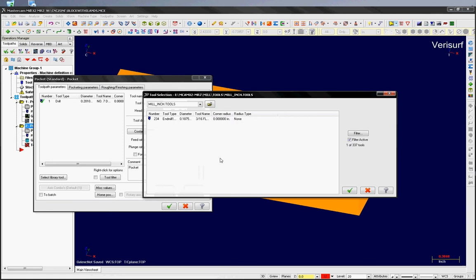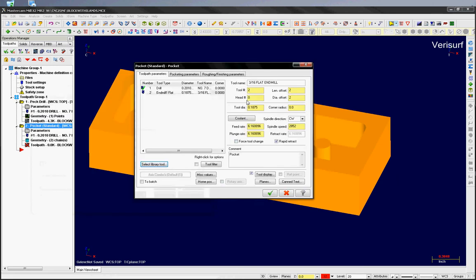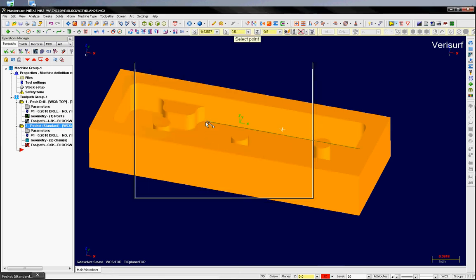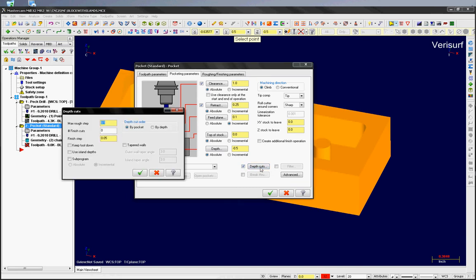I'm going to go ahead and select a tool. I will use a 3/16 at this time. Like I said, not worrying about feeds and speeds, but I am going to worry about depth. Making sure that I get the bottom part of my depth, my pocket there. Maybe some depth pocket points. Depth 100,000 pass, and I wanted to see the different islands that I picked. I picked the tops of them so it'll see each one.